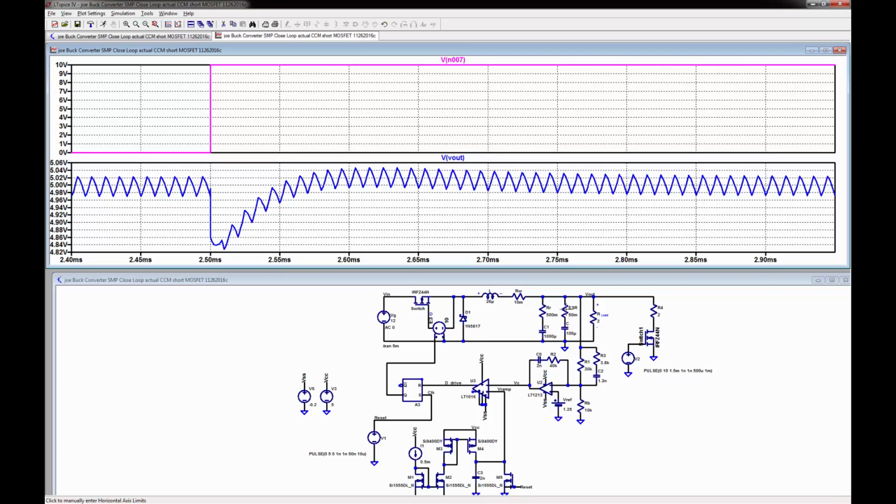Well, guess what? It comes from the capacitor. It dumps it. Hence the dump in this voltage drop initially is basically the current that this has to produce dropped through the ESR. That current is the 2.5 amps times this ESR, and that's that initial voltage. Now, what is this? Well, that's the lag of this trying to come back. So it's going to take a couple of cycles. It finally starts to come back, and now this current starts to come back in the inductor. So let's look at the current in the inductor to show you that. This is just a pulse load happening, but yeah, let's leave that in there.